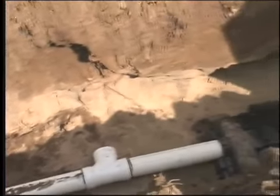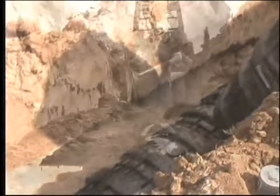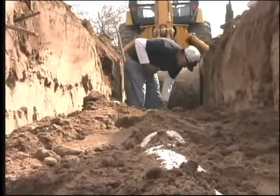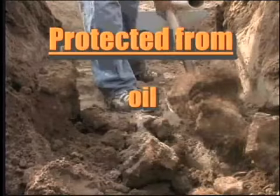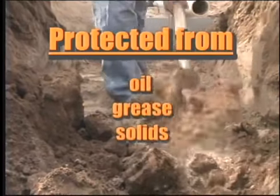The wastewater leaves the septic tank and is distributed over the drain field area. The drain field is where the rest of the sewage treatment takes place. The bacteria in the soil under the drain field treat the sewage and destroy the disease-carrying bacteria before they reach the groundwater. The soil that treats the sewage must be protected from oil, grease, and solids. This is the main job of the septic tank.